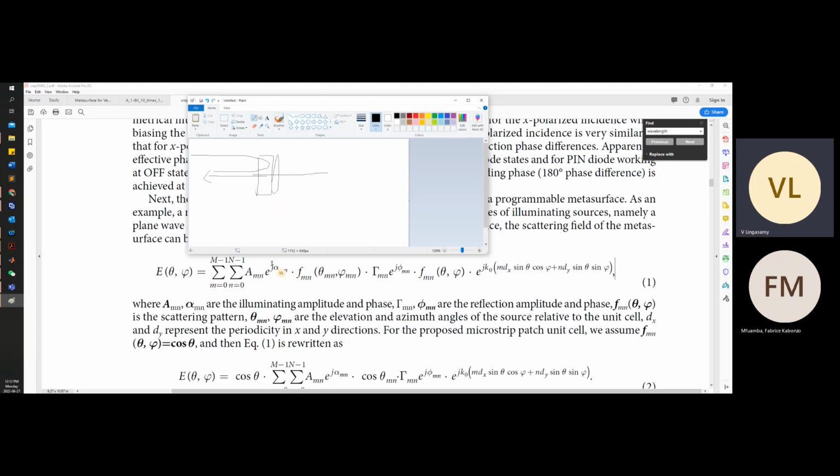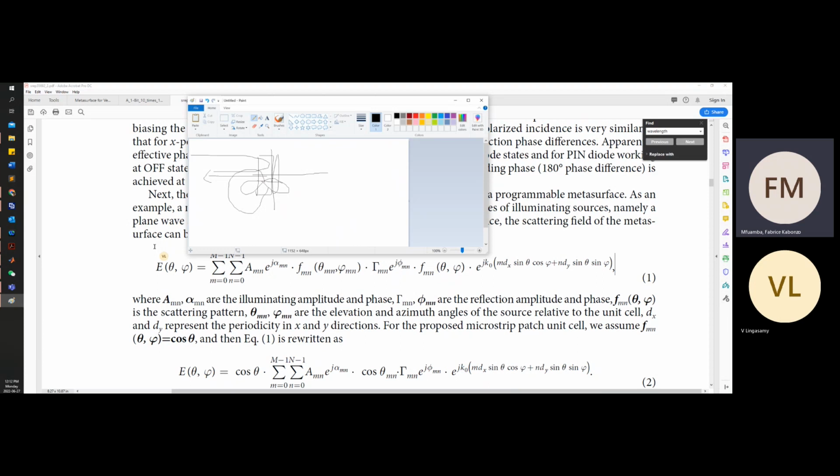The only thing is how you take the element pattern. Here, if it is a transmit array, you will have an element pattern of almost a figure-eight, because it's going to be a dipole kind of. But if you are considering it as a reflector array, then it will have a pattern like this, so accordingly this also will vary. I got it. So the transmit array is working like an FSS, right? Exactly, a frequency selective surface. Ideally, frequency selective surface, metasurface, reflectarray, artificial dielectric,